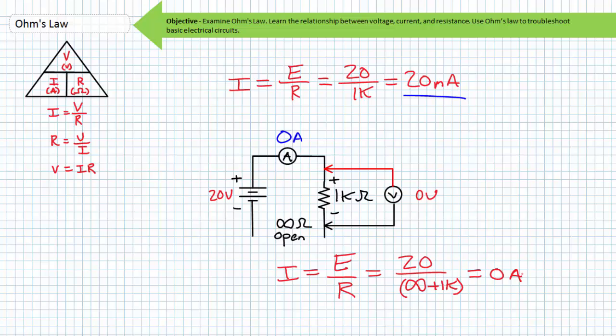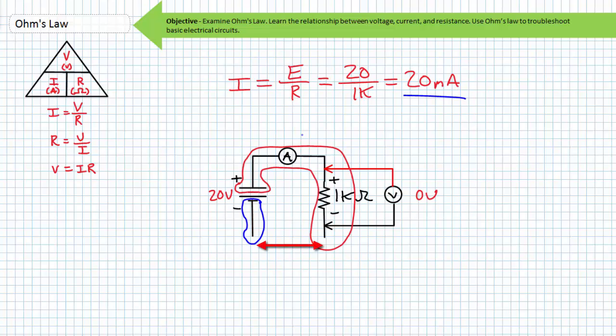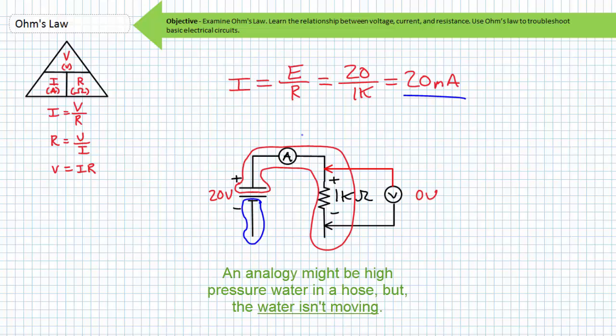Ohm's law says so. How can we use our ammeter and our basic knowledge of electrical quantities to figure out where the open exists? I know we haven't gone into details about voltmeters nor Kirchhoff's voltage law yet, but recall, for every rise there is an equal drop. If there is an open between one terminal of our resistor and the negative terminal of our power supply, across the open is where the voltage drop occurs. In this case, both terminals of the resistor are at the same potential as the positive terminal of our voltage supply, and the voltage differential between them is 0.